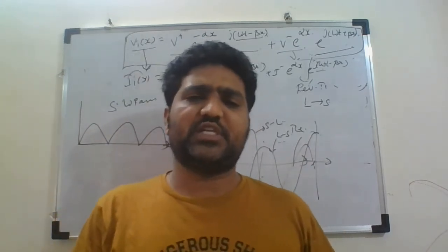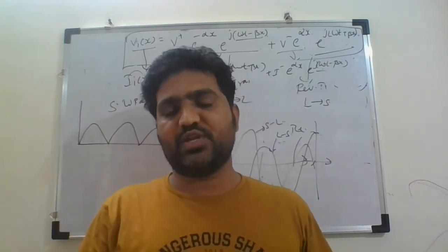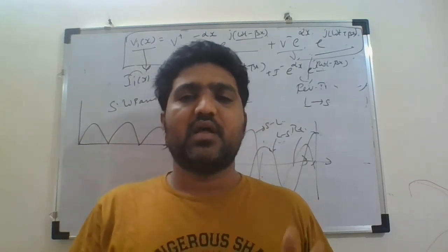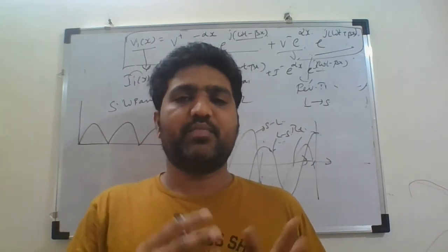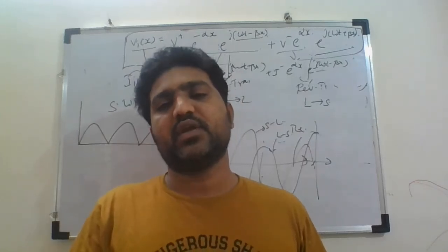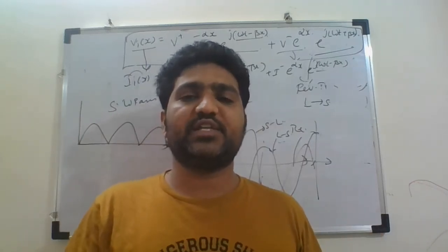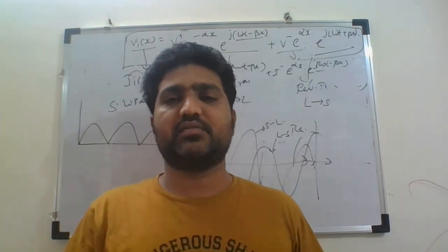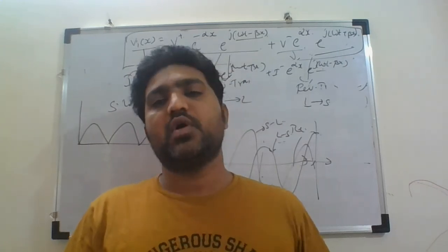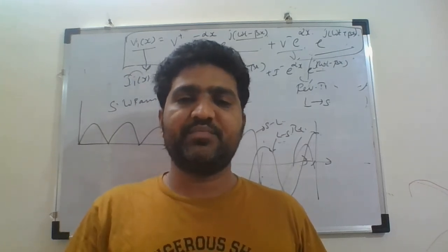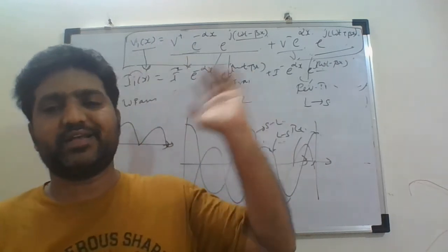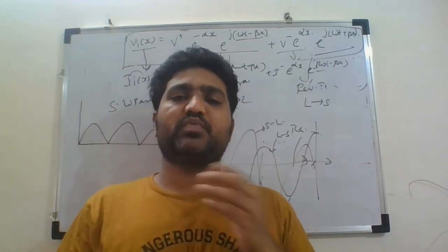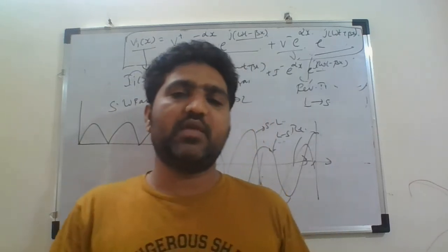So I hope you have understood. Just a quick conclusion. General solution means here we are deriving the expressions for voltage and current. For that, we started by considering a small portion of the transmission line between two points p dash and q dash. From that, I derived the expressions for voltage and current, and got second order differential equations. I solved them and wrote the general solution, and from that I observed that it has two components. Looking closely at those two components, these two represent sinusoidal variations, both the same in nature.